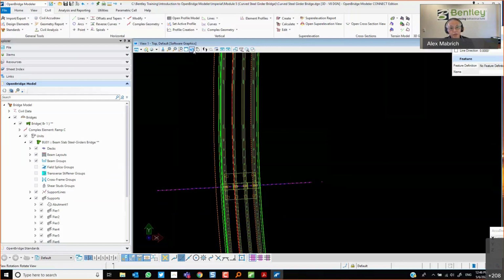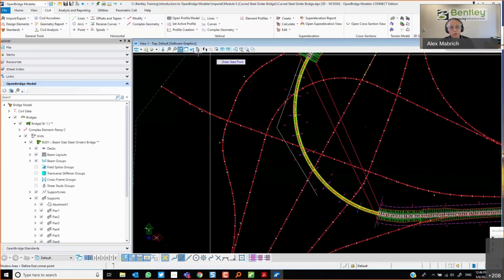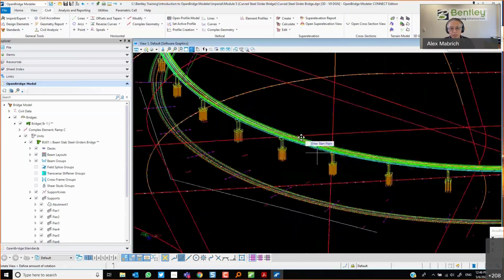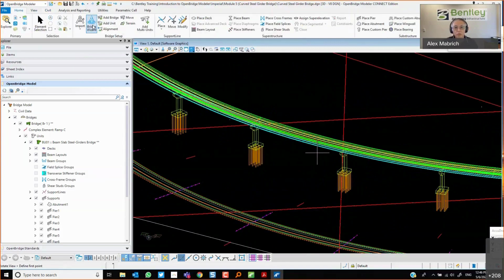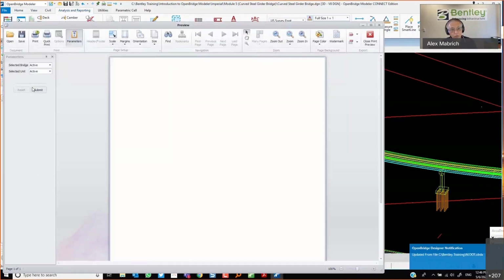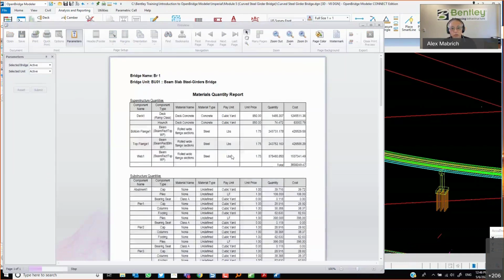So then after that, just to finish, after you got the bridge here, you can do quantities, you can do geometry reports. This is nothing different. And doing this bridge, I would say the long way, but the wizard will just give you a very quick starting point to do this and see if the alternative is feasible or not. Maybe you run quantities and decide, my gosh, this is too expensive, or that maybe I need to adjust something. Since the materials have also a price tag, a unit price to it, I can run the report and say how much it's going to cost, right?